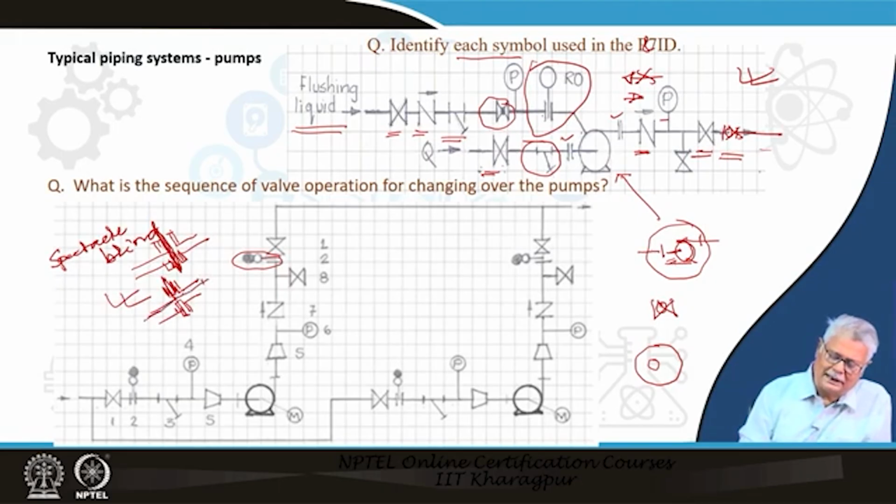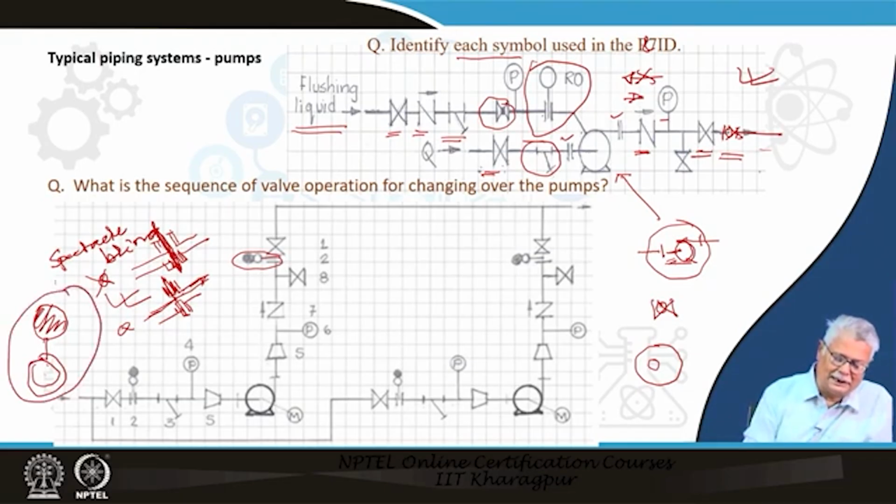So, what happens is, when I have this particular disc with a hole inside, there will be flow, and when instead of this particular disc you have something which is just a blind disc, or it does not have a hole, there is no flow there. When you have this solid disc attached to the other one with a hole, which looks like this, this is called a spectacle blind.